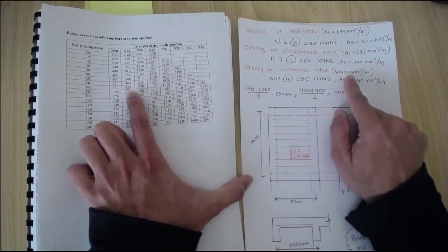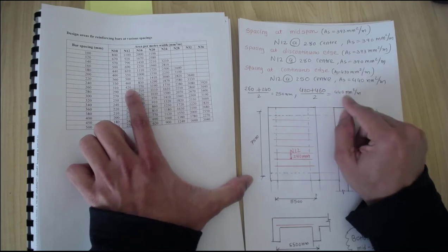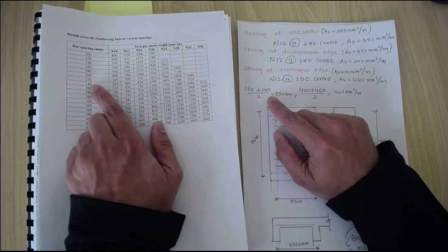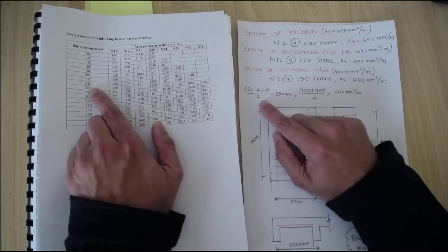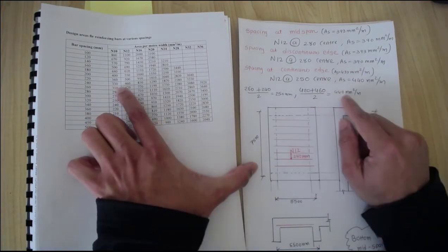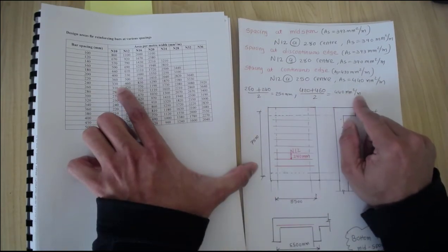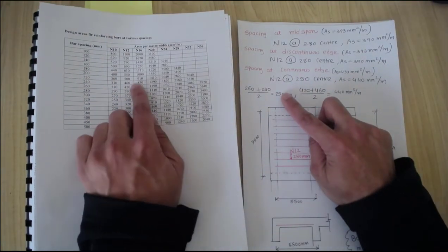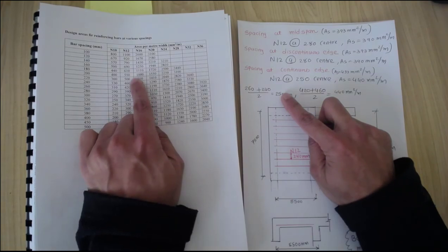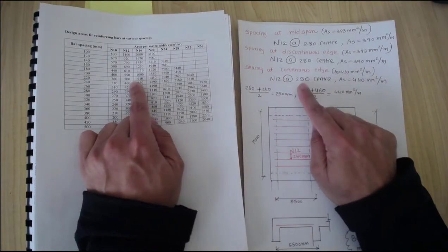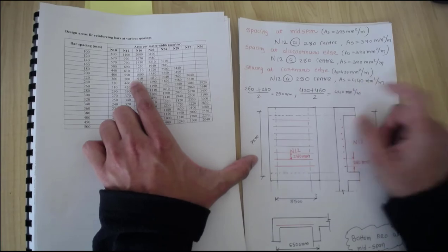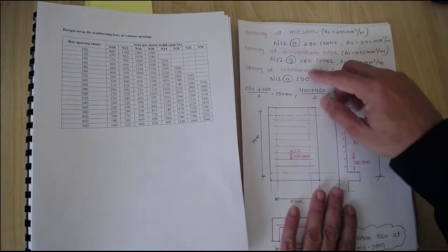So that is close here, because you are in the middle, millimeter square per meter. And similarly, we can take the average: 260 plus 240 divided by 2 gives me 250 millimeters. So for the area of 440 millimeters square per meter, we need a center to center distance of 250 millimeters. Or you can do the interpolation, as we have shown, so you can use interpolation as well. But at the discontinuous edge, we are using 250 center distance, and that satisfies this 433, which is 440 millimeters square.